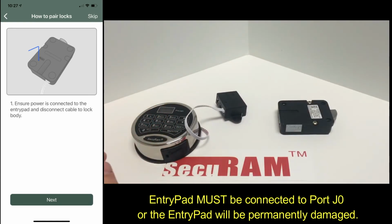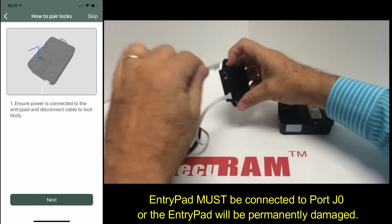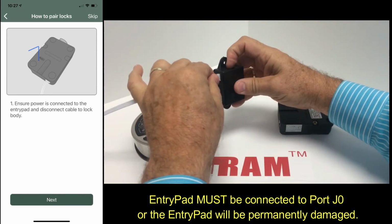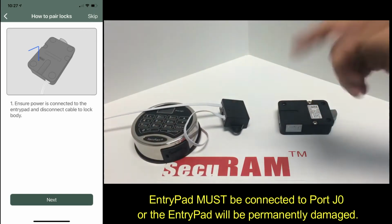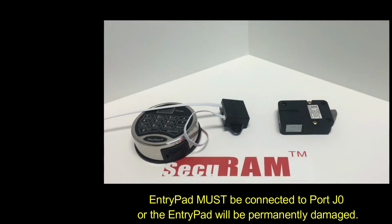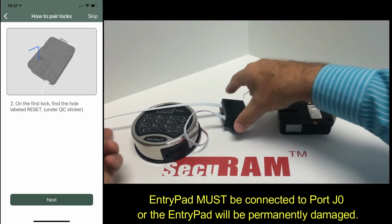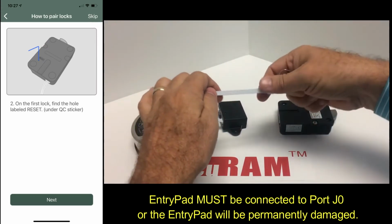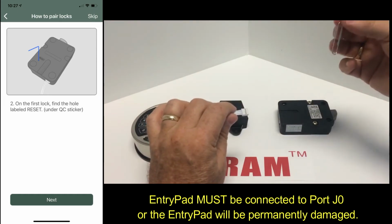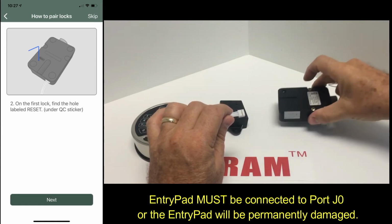The next thing we're going to do is take another cable and we're going to connect it to J1, and that is the location for the first lock. And what we have to do now is tell this first lock that it is in fact the first lock. So how we do that is we do a mechanical reset. So using the cable that I've connected to the junction box, I would take a paper clip and on the back of the lock find the reset hole.